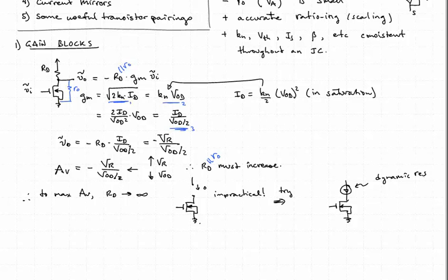And so we effectively have an infinite resistor, but we are providing a current path for biasing this transistor. We have ro, and now the voltage, I shouldn't put the small signal on here yet because I'm showing this bias current.